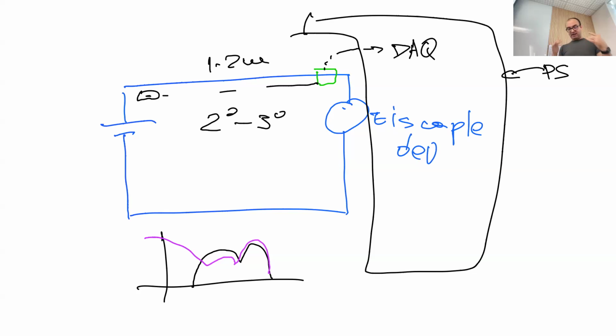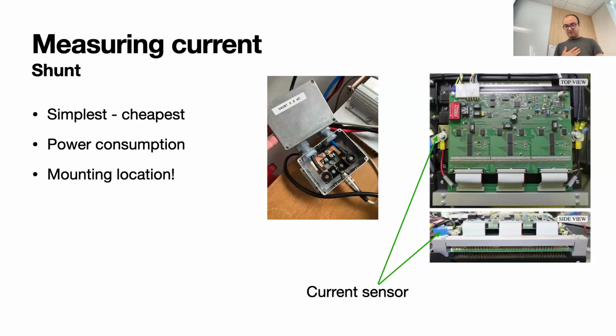So that is why, and a normal electrical engineer would say, well, yes, but you never think that the influence is so high, because when you put the equations down, you will see that it should be like this, but by heart you don't feel it. So that is why we always try to measure current as close as possible to the fuel cell itself.